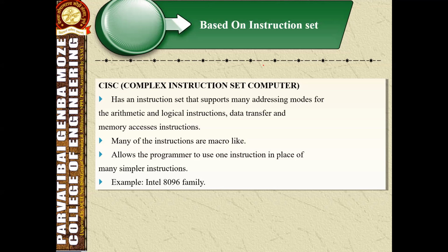For example, in the 8051, the multiply instruction, short form MUL, is a complex instruction for which only the operands need to be specified in the instruction. The multiplication operation is done by hardware. The building of complex instructions in hardware helps the user in two ways. Firstly, the implementation becomes faster, and secondly, the program space required is less.